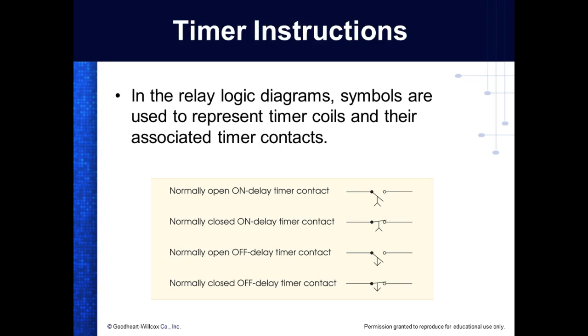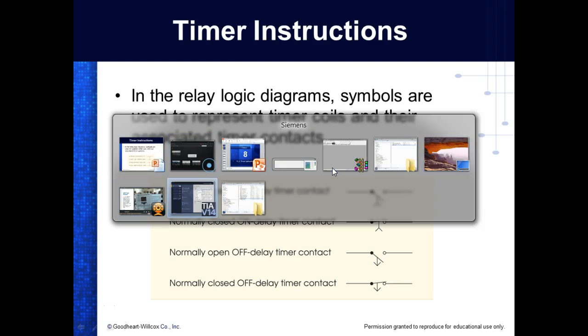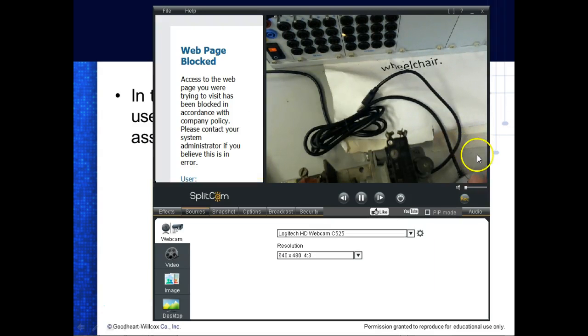The relay coil for a timer, so all a timer is basically, well, most of our timers, we have different types of timers. We have what we call dashpot timers, which basically has a diaphragm that's full of a liquid. And then when we energize it, it's got a spring that tries to push it into another diaphragm. And what you do is you control the size of the orifice that the liquid goes through. And these are called dashpot timers. And these are still all over the place. They're very, very simple.